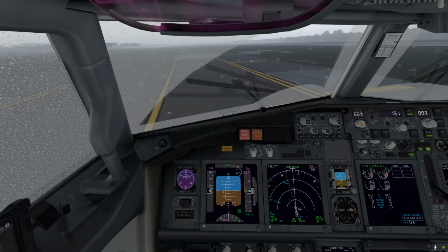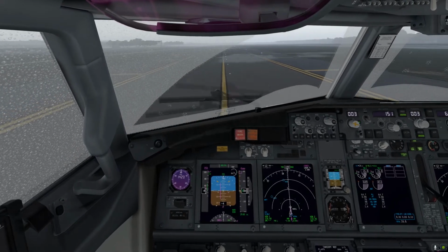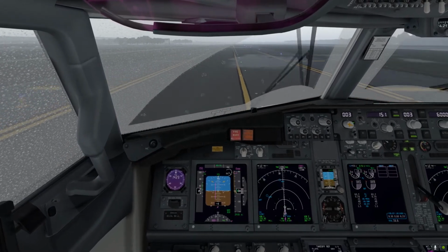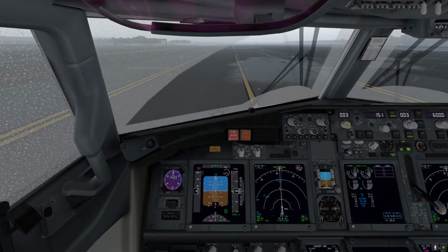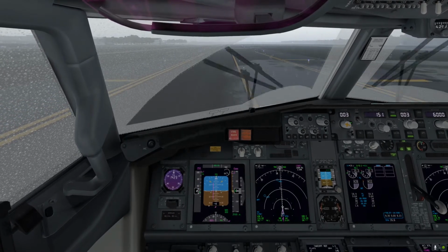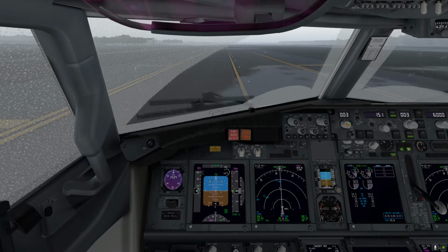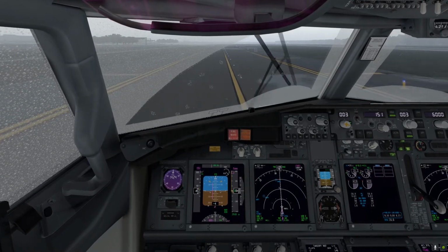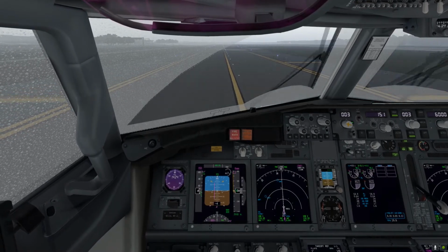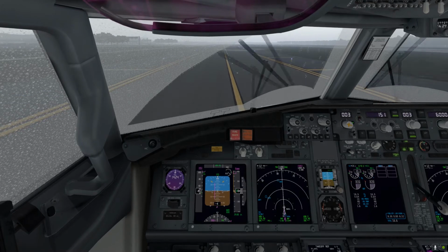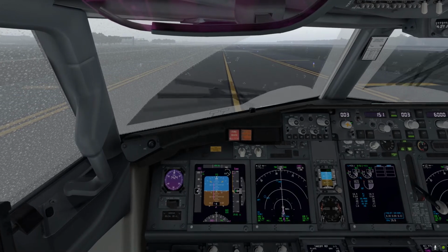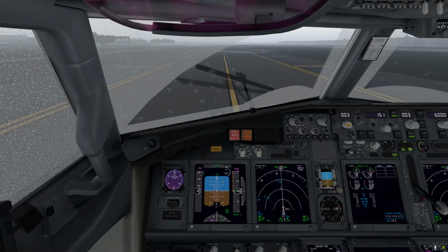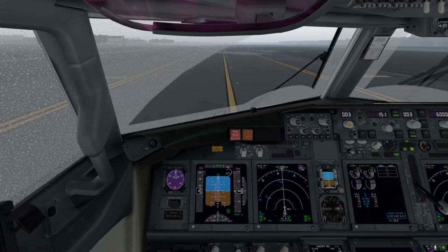Okay, I've just downloaded the latest ATIS for Tampa, and it says now wind is 120 degrees, 11 knots, gusting 25. So it's much more important to use runway 19, because actually the wind is coming from southeast.